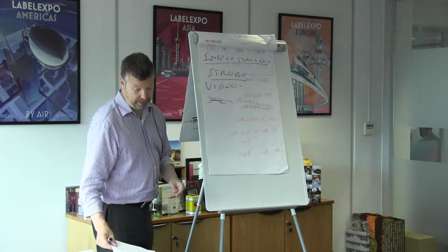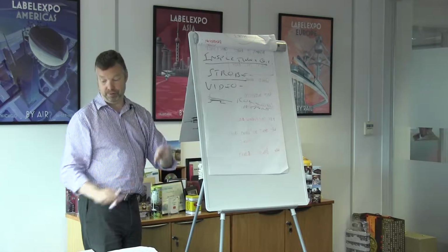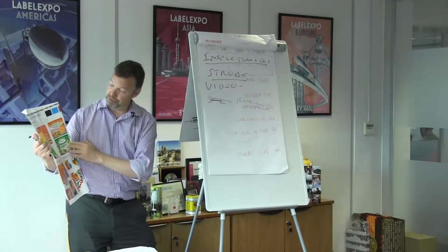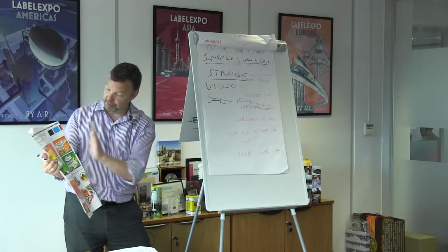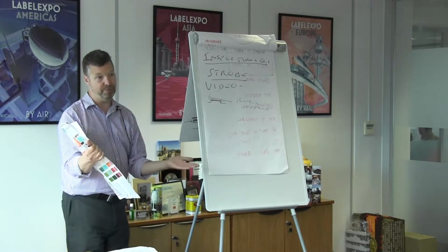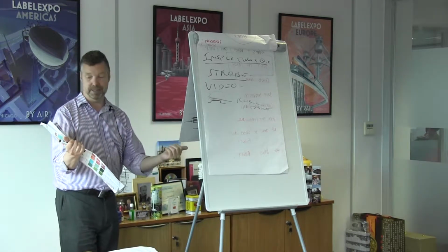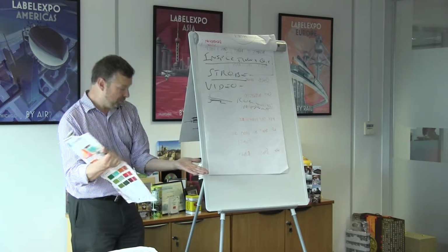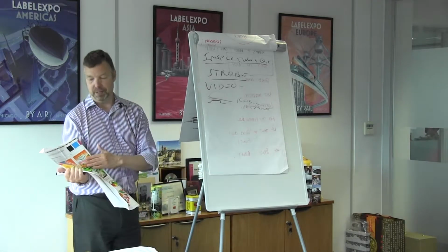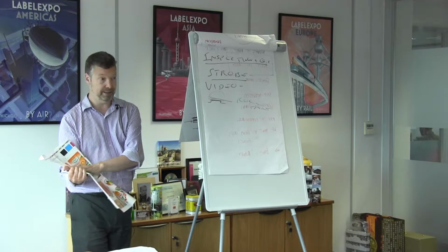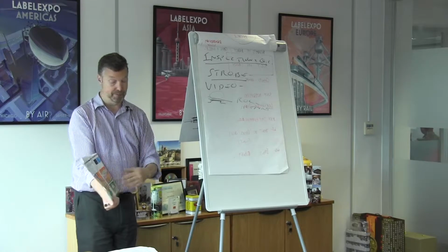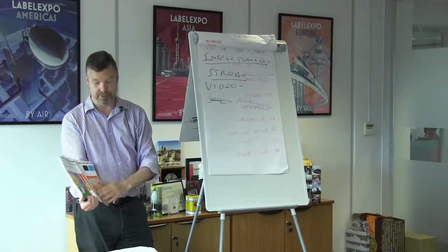The second big development is doing away with this golden image. The idea we were talking about is that just before the job starts, when you've made ready and you're about to ramp it up to speed, the camera takes a photograph of the first label it sees and uses that as a reference. But as we've said before, the problem is you can't do any variable data, because it will only look for whatever the data code is on that one label you photograph. So it can't look at serial data, it can't look at color, and it can't look at whether that image is actually right or not, because it's just taking a photograph of the image.